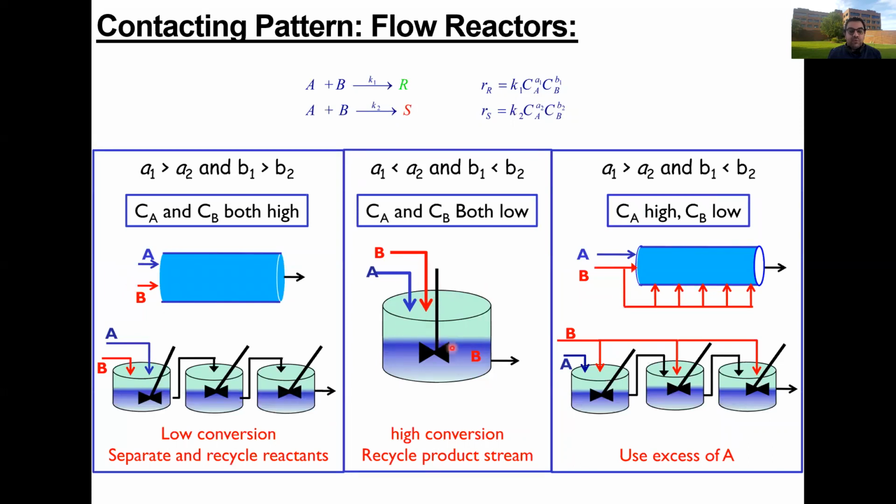If I want to keep them both low, I introduce them both at slow flow rates into a CSTR, maybe filled with an inert. You don't want to introduce them slowly in a PFR because PFRs are usually pressurized vessels, and you don't want to have vacuum, or you always want to keep the flow matching the pressure. You can always pressurize this with an inert, however, separating gases is more complex than separating liquids. Anyways, but these are ideas for later on.